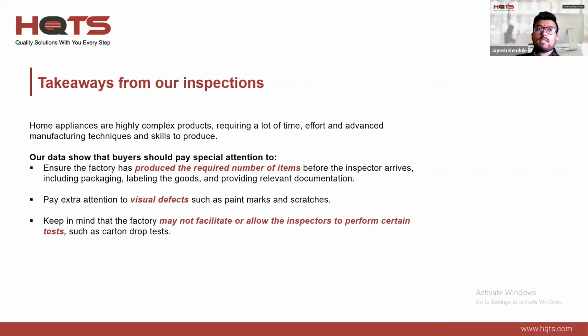So, as seen from the past working with major manufacturers, what I have personally analyzed is that certain times the product is working fine with the safety requirements. When we adhere to the compliance requirements, safety and EMC requirements, like electromagnetic radiation reports, those are the major parameters checked for the home appliance categories. So the safety requirement is sometimes fulfilled, but the EMC requirement is not, because of one component issue. You need to go back to the development stage, change the particular component, and then again do the compliance and all the things.